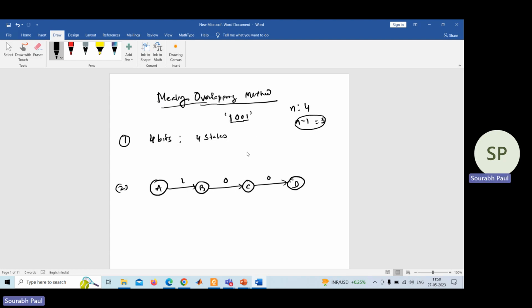Okay. Now after that, whatever values we have put here are nothing but the inputs from one state to another state. To go from one state to another, the inputs you are providing are what I've written. Okay. Now after that, I need to think about the remaining input, because for each state, how many inputs are possible? The possible inputs are 2, either 0 or 1. So we need to see which inputs we have already used and which need to be used.